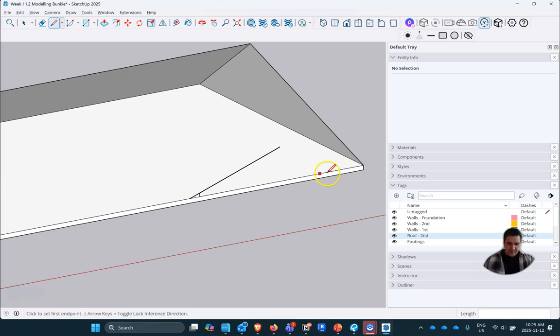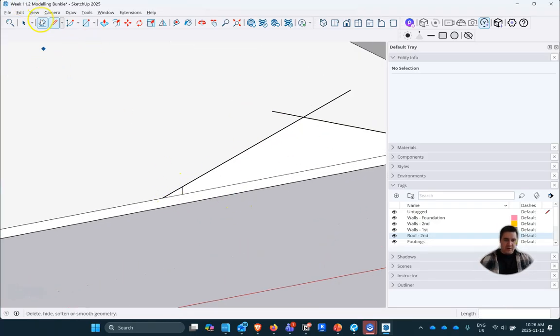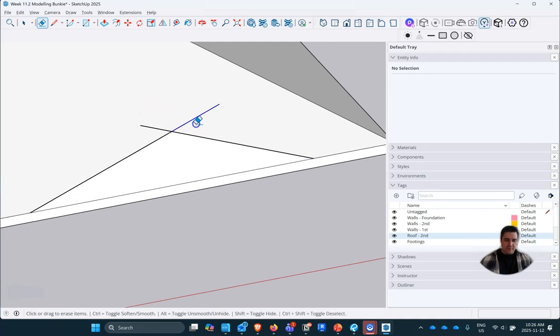And let's find our piece over here. Let's go in 12 inches. And we'll go up our 5 inches here. And back down to our point. Find that intersection. So there's our dormer, so to speak. With this, again, we could extrude this, or we can just bring that line back. I think I'm going to extrude it just to make my life a little bit easier.